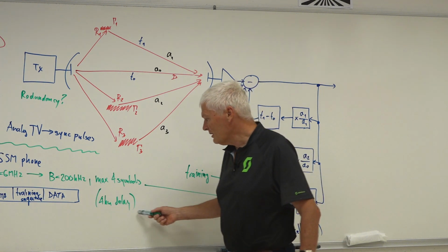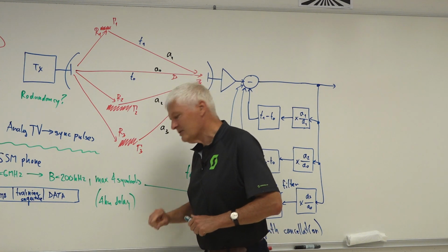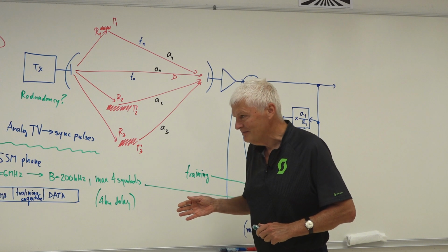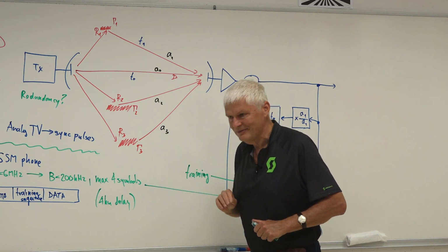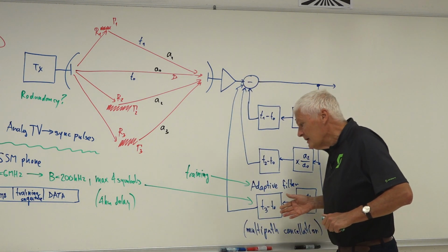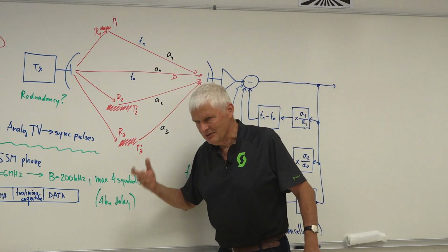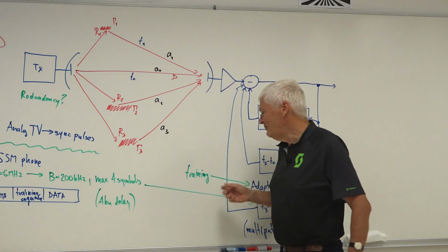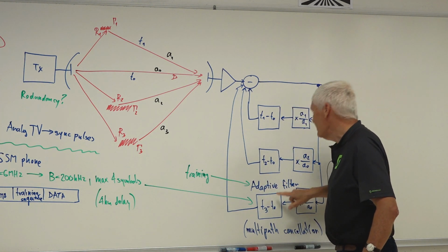So this thing worked fine in the flat regions of France and Germany. It didn't work in Switzerland, and doesn't work in Slovenia anyway. In Slovenia, for instance, we typically have the delays of 10 kilometers because of the mountains. So the filters that are actually standardized for GSM phones are actually too short.